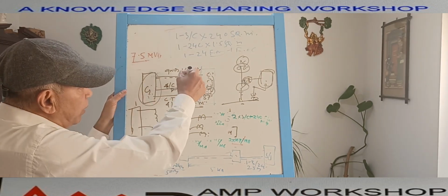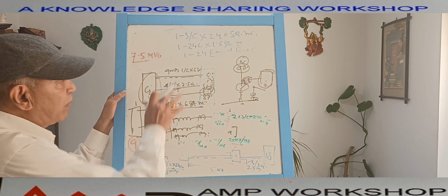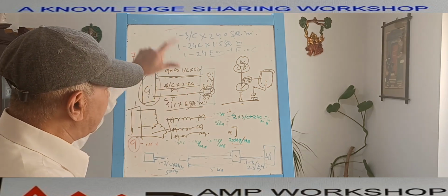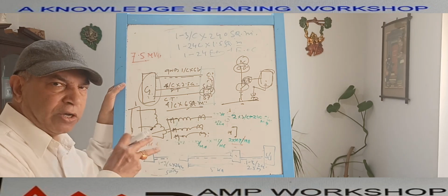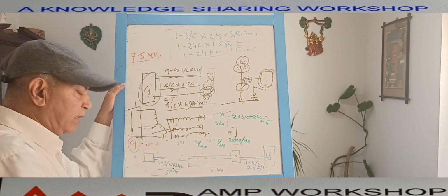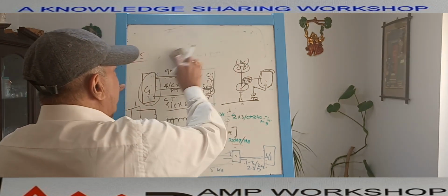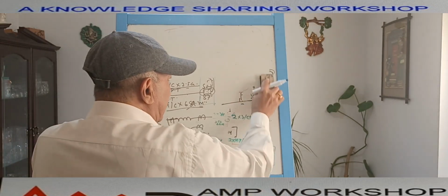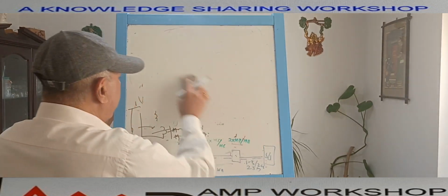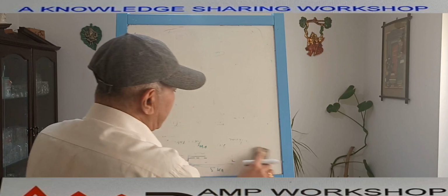So this cable also has to be shown in this drawing. We can lay it, and the length and all these details are already there. These have separate numbers that we can also include. In this way, this power cable block diagram can contain the major power equipment and major power cables, as well as the CT and PT cables. In addition to this cable block diagram drawing, we can make a small table on the right side or on the bottom of the drawing to demonstrate a summary of the various cables, the laying method, and the estimation of the various types of cable.